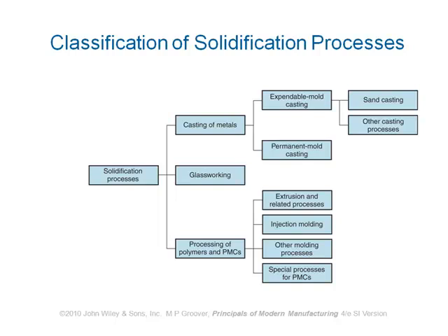However, in permanent mold casting, often metallic dies are used in order to produce the part. As it's a metallic mold, we should be able to open it up and to take the part which is inside the mold out of it. So there is a mechanism of closing and opening the mold system in order to take the produced part out of the cavity.